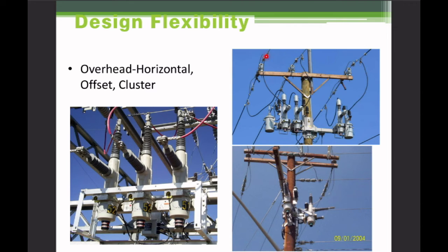Or if it saw energy flowing through, but it knew there was a fault in this segment and the power went out, it could, during that outage interval, because it is so fast, open itself up, segmenting our system so that when the power came back on, it would flow to this switch, but not through it, therefore isolating only the faulted system downline.